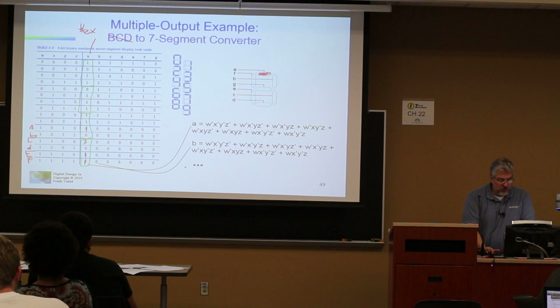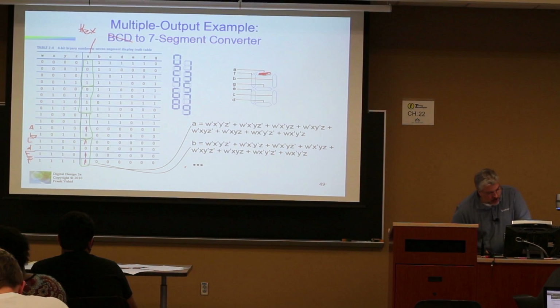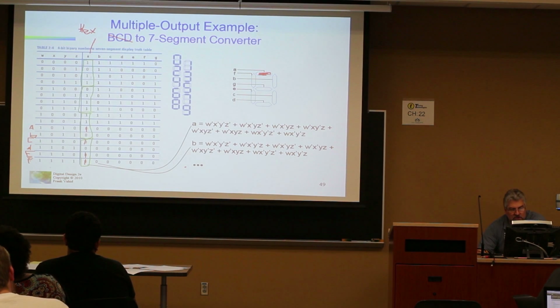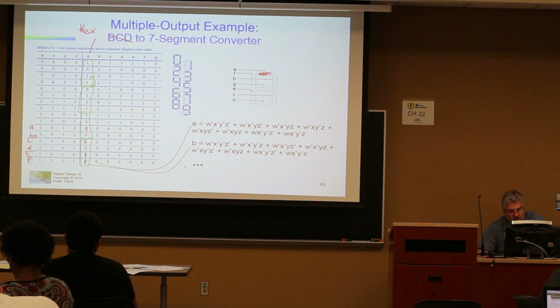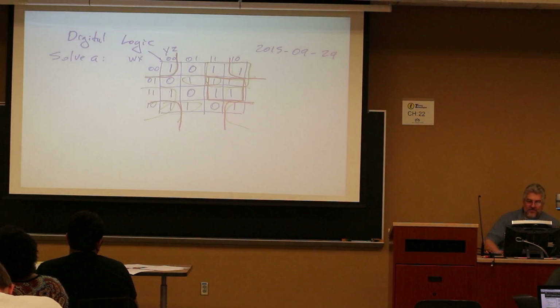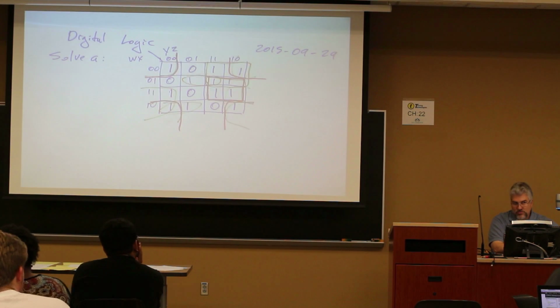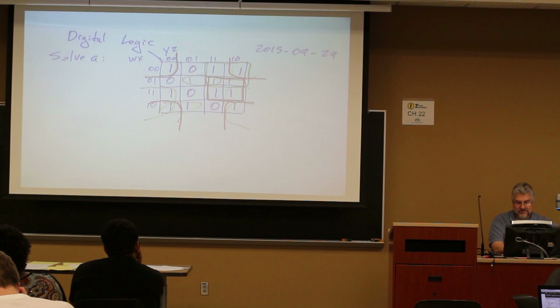Specifically that column, we put it in the lines. Now one thing to note is this is the first line, this is the second line. Remember we swapped these two in your Kmap, right? This is your second line, this is your fourth line, this is your third line. So the representation I have for that is this. Do you agree with that? Yes? All right,